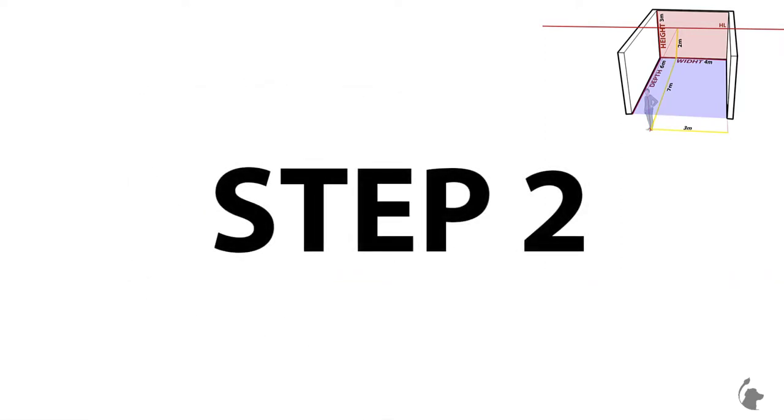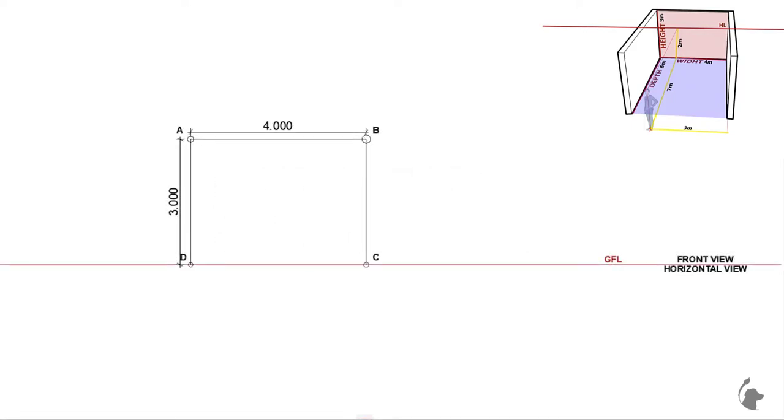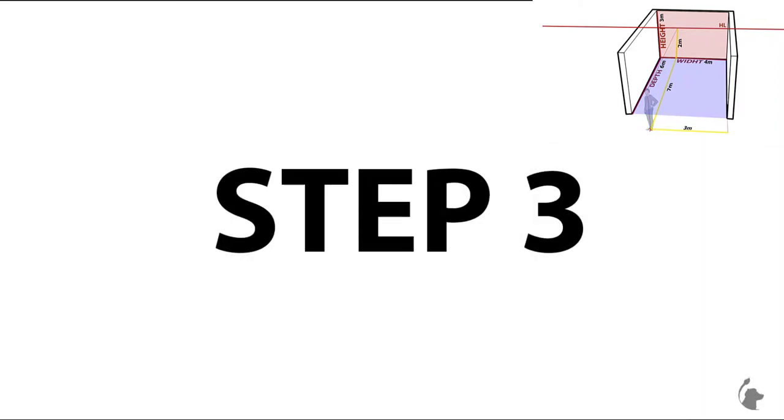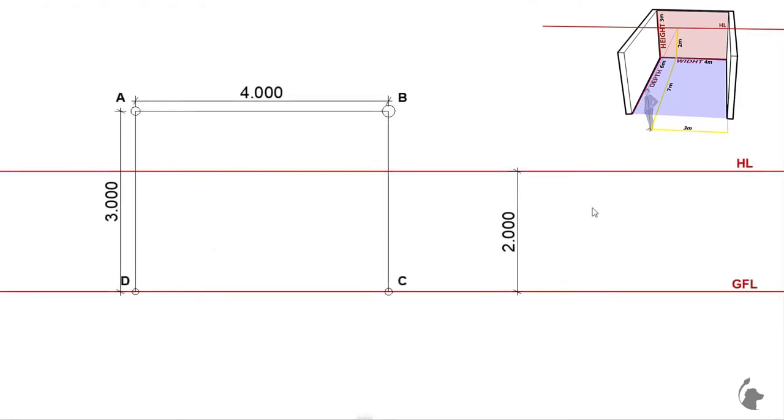Next, step 2. We will draw our eye level, which will be relative always to the height of the drawn environment. In this case, it will be at 2/3 from the ground up, since we're 2 meters high and the ceiling is at 3. As we learned in the previous lesson, this is a horizontal line parallel to the ground plane line.